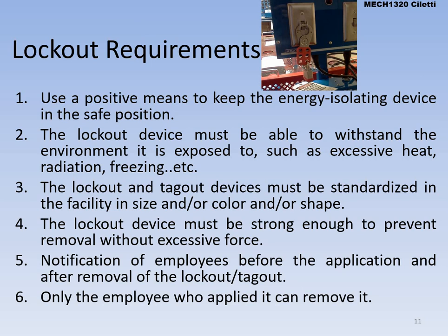Also make sure you notify employees before the application and removal of it. So let everybody who's working know. Hey, we're locking this out. It's going to be down for maintenance, down for 20 minutes, that sort of thing. Hey, we're bringing this back online. They knew that you were locked out, tagged out, but they might have been in the vicinity. They could be in a dangerous location. So make sure that you're giving people an alert. Hey, systems firing back up.